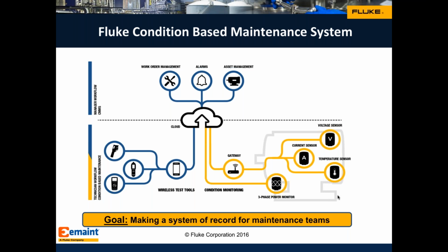We say, hey, we know you're doing PM. You may find that this motor needs to be looked at for the next 3 or 4 weeks because you have a suspicion, or the initial PM has shown you something, so you need to monitor it on a regular basis. Condition monitoring is a big piece of it. At the end of the day, as long as all the data ends up in the cloud, through alarms, work orders, condition-based work order management, or simply route-based, this is a critical aspect.